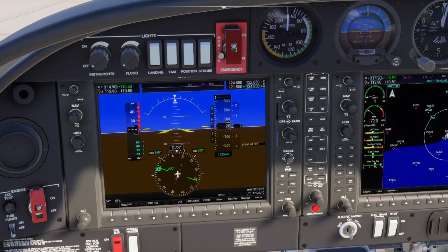Then you come back, go PFD options. You can turn on the wind, so I recommend option 1. A DME if you've got a DME, so we can put that on. And then bearing 1 and 2 can give you GPS, nav1, nav2, or ADFs. We won't need that for today's flight, so we can leave that off.